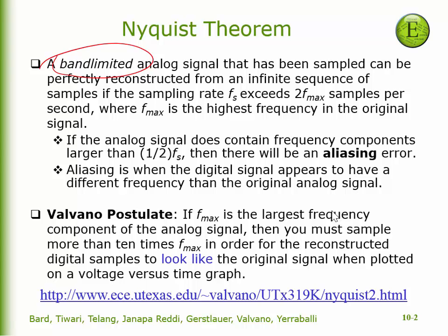But something very unique happens when you digitize the signal. And it's called aliasing. We'll talk about what aliasing is in a second. So we have to make sure that anything beyond 20 kilohertz is gone. And that's easy to do. We stick in a high resolution low pass filter and it chops it off.